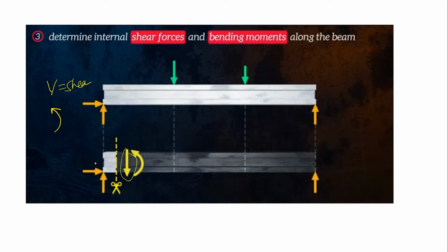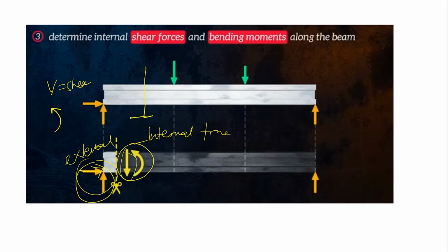Of course, it also includes the axial forces. So this is external, a right or left reaction, and this is internal. Internal forces. And what is the significance of these two forces? The internal forces should balance, should counteract the external once you cut. So how do you cut? You cut it here. So you will have the internal forces. And the internal forces should balance the external. That is the way to analyze.